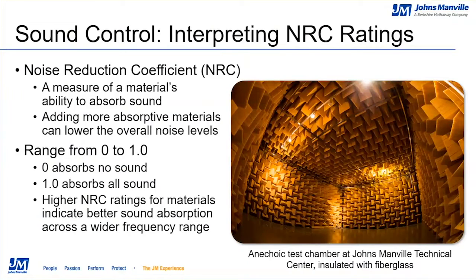The higher the NRC rating for a material, the better it will be at absorbing sound across the typical speech frequency range. You may occasionally see an NRC rating that exceeds 1, but this is a result of how the material is tested. I should mention here that architects or designers may work with STC, or Sound Transmission Class ratings.